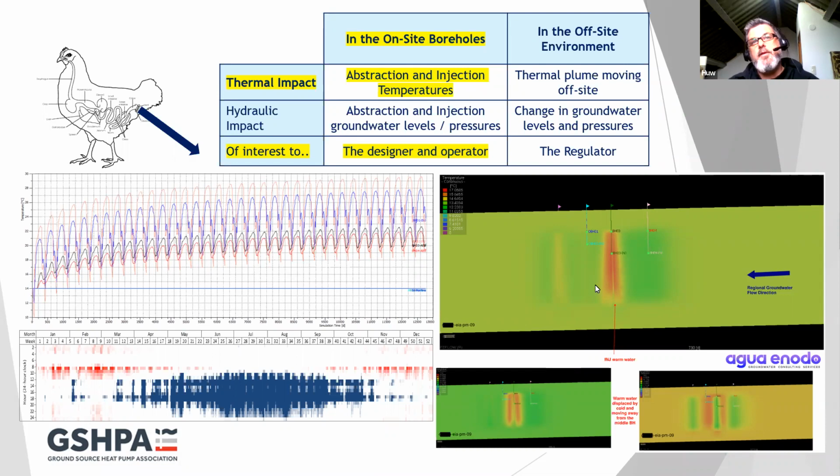And on the other side of that, we've got 3 cross sections cut through a 3D model of an aquathermal energy storage. We've got the boreholes modeled as little flags, like little golf flags, and you can see that over time, in these 3 different screenshots, we've got thermal energy, a bubble of warmer water, being stored in the ground, moving away from the borehole and then being drawn back according to the interseasonal storage that this aquathermal energy system is trying to predict the behavior of.